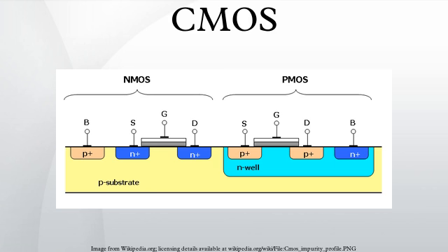The phrase metal-oxide-semiconductor is a reference to the physical structure of certain field effect transistors, having a metal gate electrode placed on top of an oxide insulator, which in turn is on top of a semiconductor material. Aluminium was once used but now the material is polysilicon. Other metal gates have made a comeback with the advent of high-K dielectric materials in the CMOS process, as announced by IBM and Intel for the 45-nanometer node and beyond.